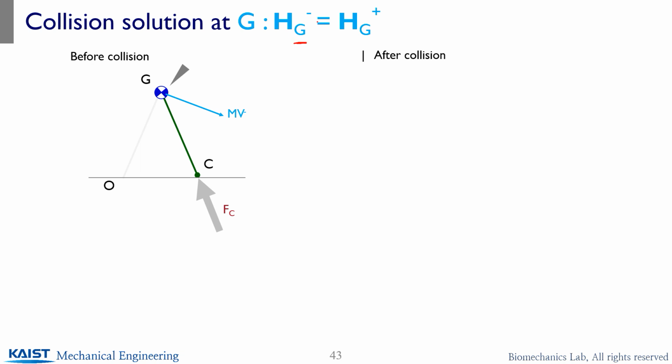Like the angular momentum about the center of mass G before collision is going to be conserved for after collision. So, to expand further, let's focus on the direction of this impulsive force F of C. Is F of C aligned with the leg? Well, in the previous case for the rimless wheel, yes, because the leg there is welded.